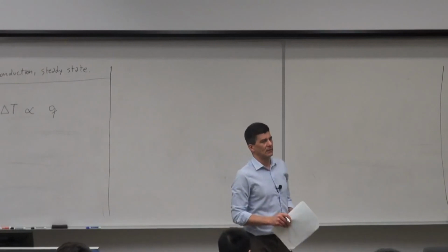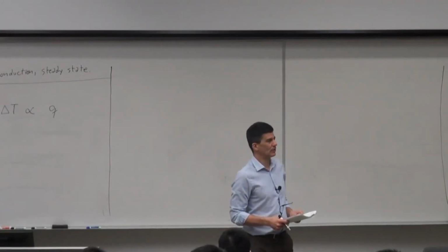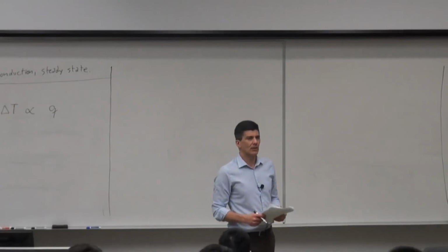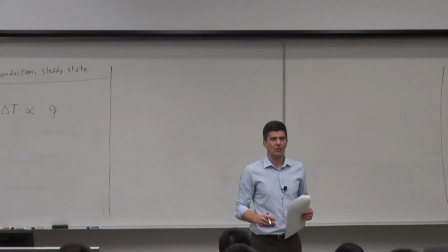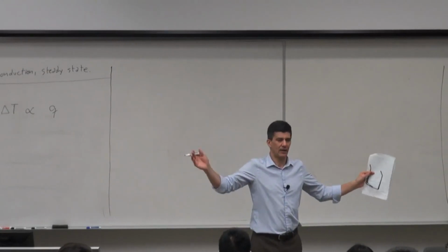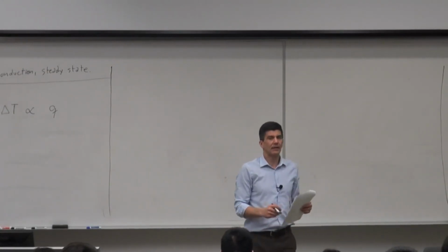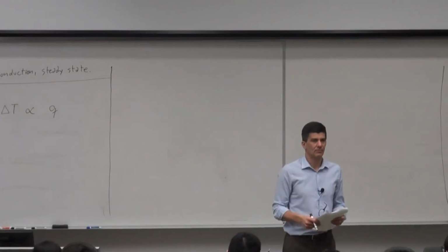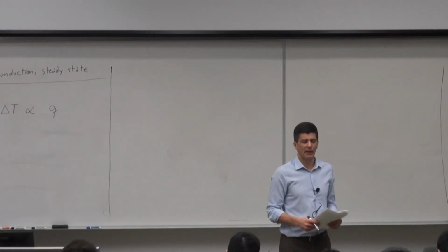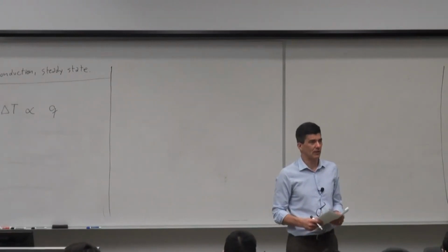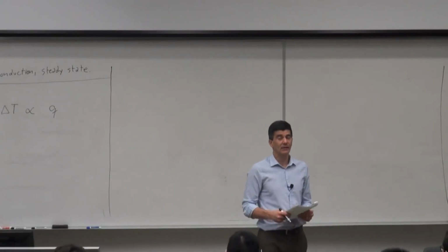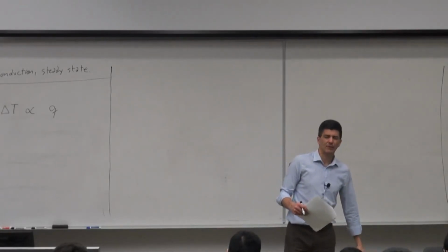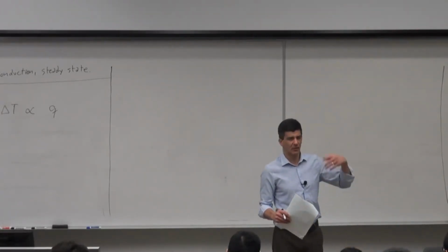Now this idealization is very useful. For example, something I didn't mention to you, but imagine you're calculating heat transfer on a big tank. Big tank, and the wall is relatively thin compared to the diameter. So your wall is not plane anymore, it's a cylinder now. Now the cool thing is, just like we think this table is flat, but we know it's not really flat, because the Earth is round.